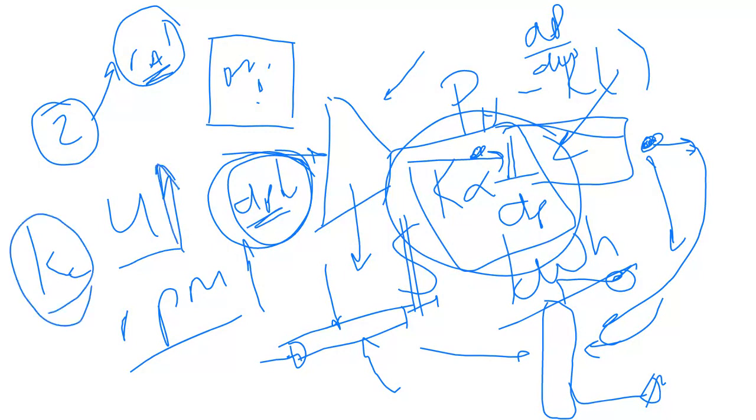If I increase my linear velocity, an increase in the pressure drop. If I decrease my particle diameter, an increase in pressure drop. If I add an inert, I'm going to increase the mass flow rate in my tube. So I'm going to increase my G value, increase in pressure drop, right? So pressure drop can affect the rate, but not to such an extent. The kc will always win that battle when I just look at the reactor performance, the kc and the heat transfer rates.